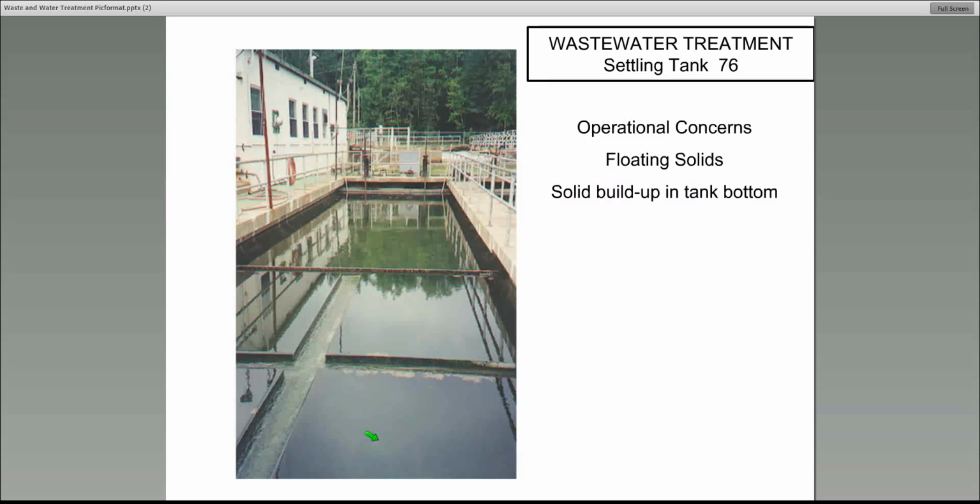This is an old wastewater treatment plant. The flow is coming from the bottom going up to the top. These are overflow weirs that skim floating material, oil and grease off the top, and then that's taken for other types of treatment. And then once it goes through these overflow weirs, you can see there's a divider here,